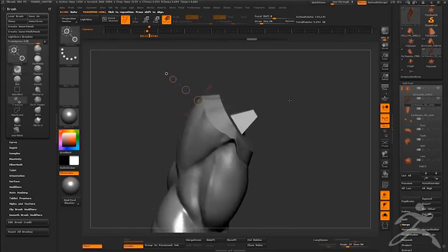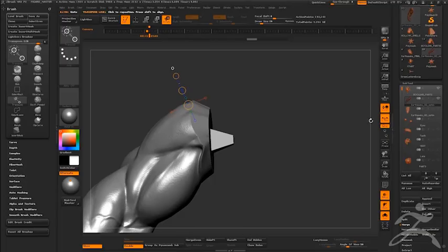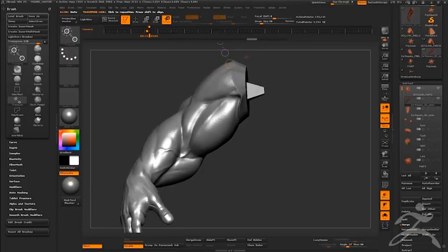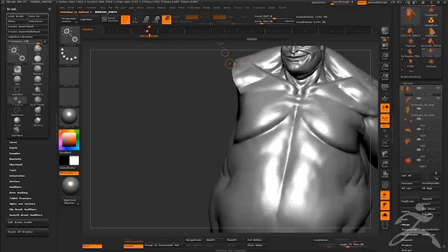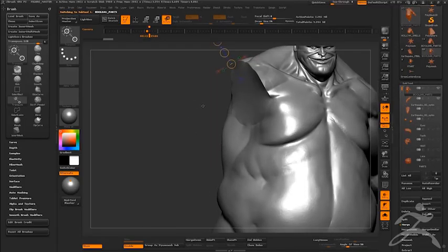I only want to do one more thing before I create this Boolean join here. I want to duplicate this key exactly in the same location, and I also want to scale it up just a little bit so that the socket it's creating in this part of the model is just a hair bigger. The problem with keys is if they're made perfectly to join each other, there's no room for glue. It's really hard to get the parts together, and you're frustrated.